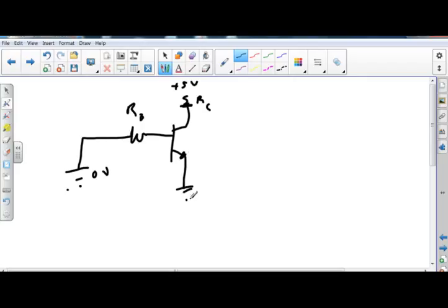And I'm grounding on this side. Because there's no voltage at the base, I'm at 0 volts, this guy is off. So if I go and have voltage out be right there, what is the voltage out going to be? If I have 5 volts here and the transistor is off, there's no current flowing through it, that means I have to have 5 volts coming out.